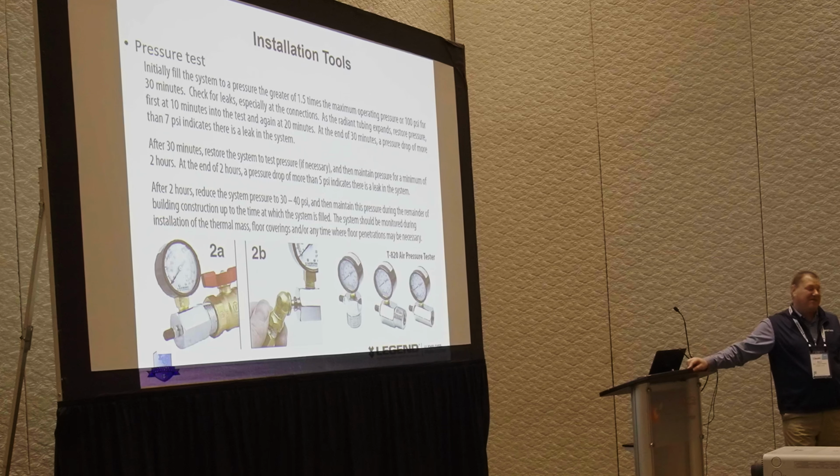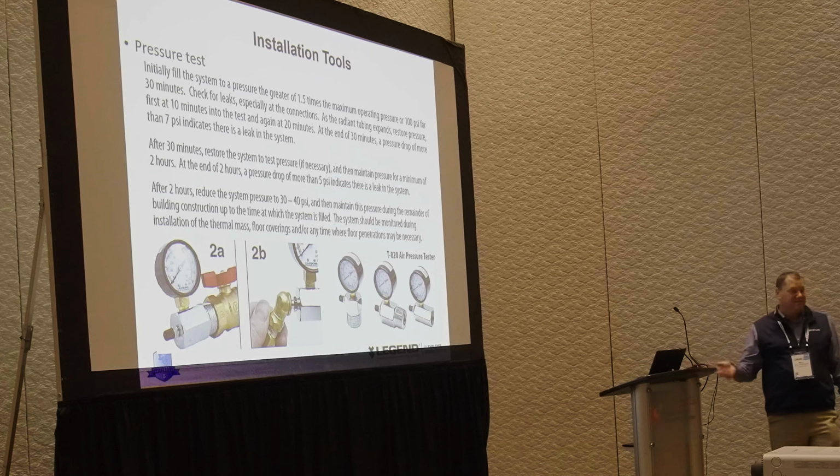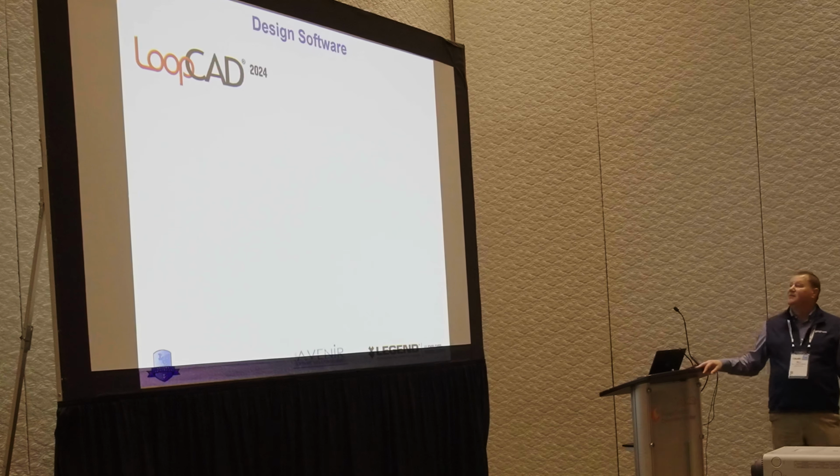If you notice that it's down... I did pressure tests in a building. We went back 4 years later to install it, and they were still holding pressure, which told me that we don't have to worry about this system. We can bleed out the air and commission it.